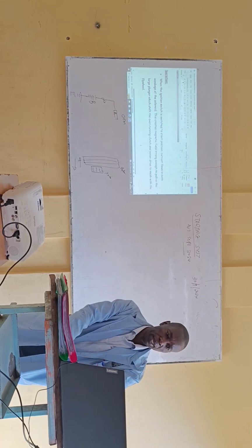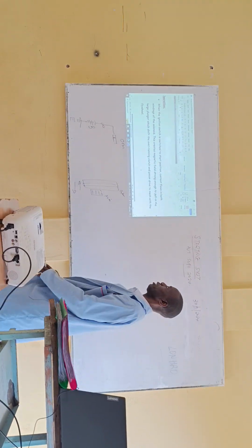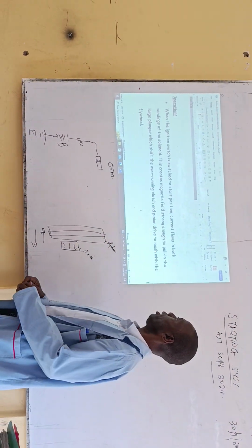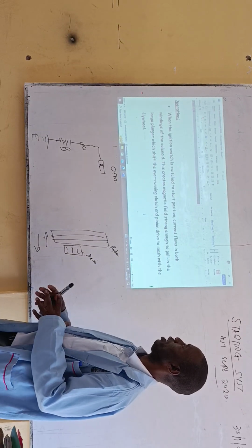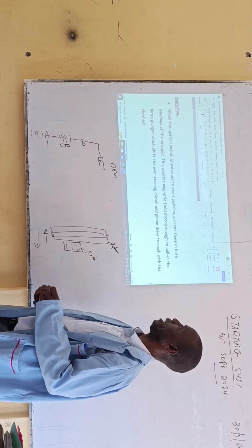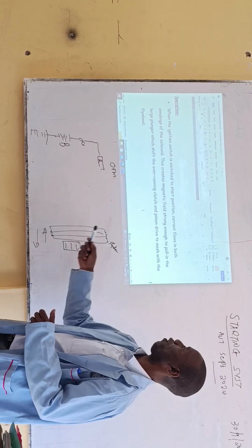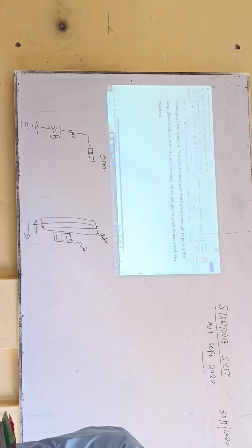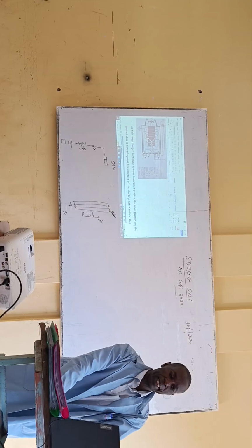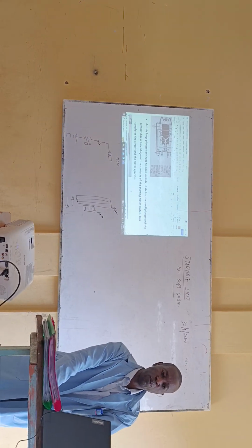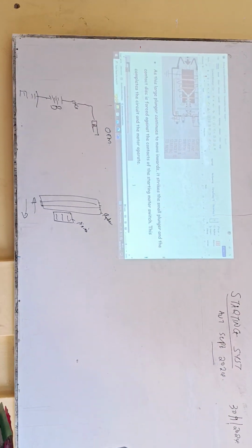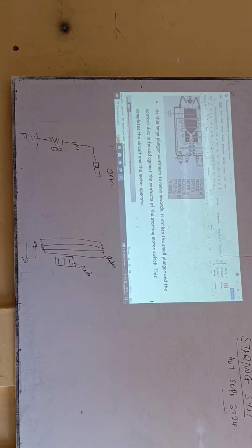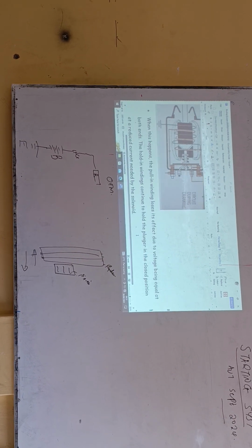So we are talking about the operation as we finish. When the ignition switch is switched to the on position or start position, the current flows in both windings of the solenoid. This creates a magnetic field strong enough to pull in the large plunger, which shifts the overrunning clutch and pinion drive to mesh with the flywheel. Just as simple as that. And you realize that as the large plunger continues to move inwards, it strikes a small plunger and the contact disc is forced against the contacts of the starting motor switch. So this completes the circuit and the motor operates.